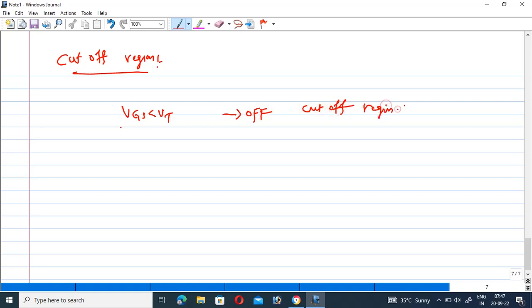So this is related to the metal oxide semiconductor field effect transistor, guys. It is very easy, guys. If you know the one logic, definitely you can form the P-type enhancement MOSFET. You can just change the corresponding substrate. So the P substrate is replaced by the N substrate, N wells are replaced with P plus, and as for the gate supply voltage, you have to apply a negative voltage, that is minus VGS.